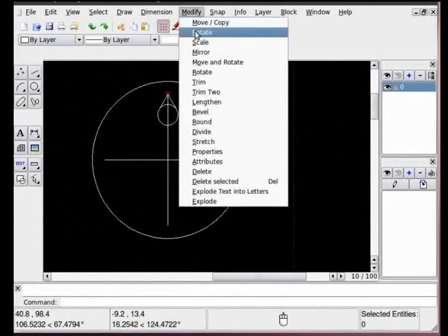Here, this first rotate tool can create single or multiple rotated copies of an object. Right below there is Move and Rotate, which will let you rotate objects with a specified distance and create multiple copies. But we will choose this rotate tool, which will let me create multiple copies of objects going in a circular direction around a point. So select that.